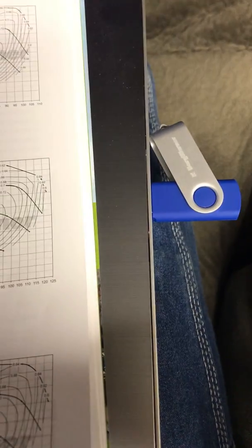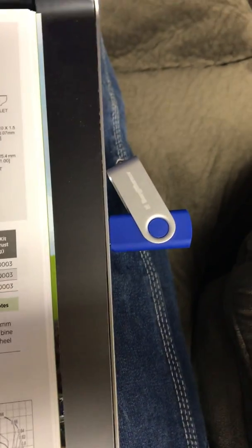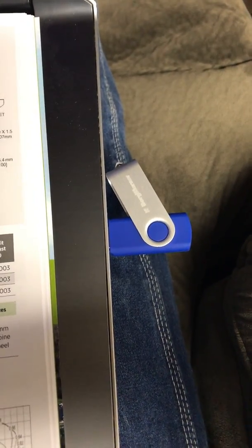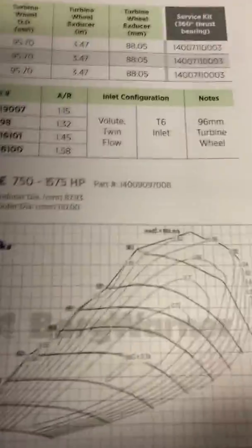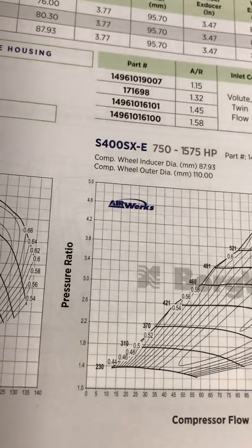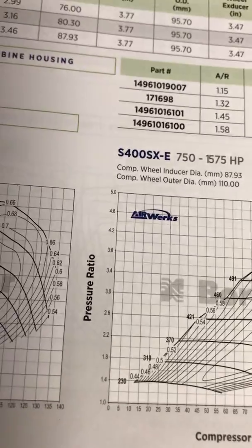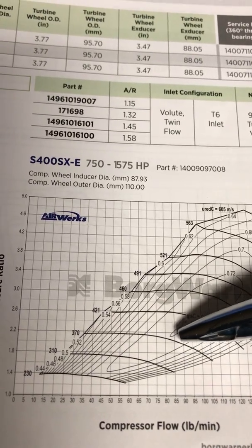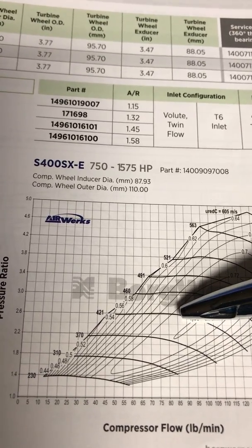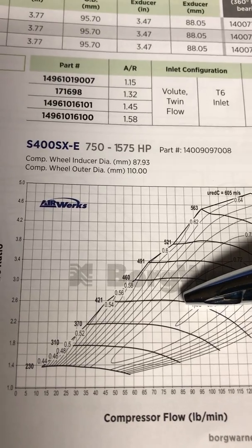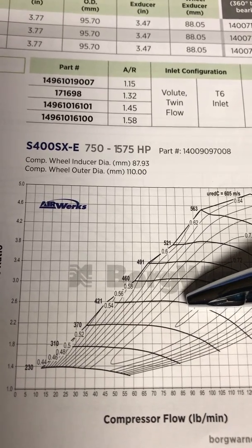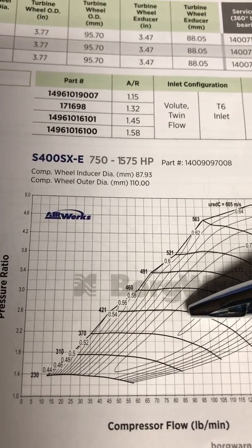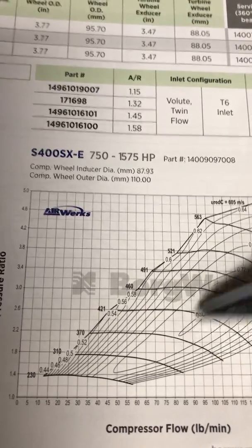See, that's why compounds are so good. You're starting out with a big turbo, and you're not asking a whole lot of it, and you're asking a lot less out of your little turbo on the manifold too. Here we go. Here's that 488. That's fairly new. Between 85 and 90. Take that up to 2.6 to 1 ratio. 26, 27 pounds of boost is all that is. And that's sweet. You got it right there in the sweet spot.